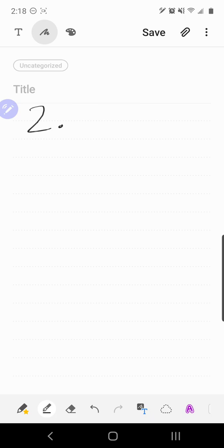We have, at the start of our compression in an air standard Otto cycle, a compression ratio, which we're going to call RC, of 10. And air is at pressure 1. Air is at 100 kilopascal and 40 degrees Celsius at the start.